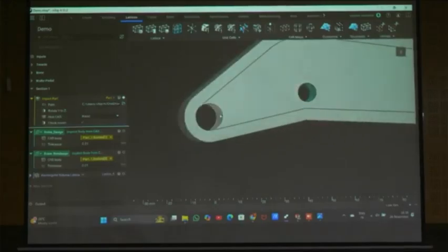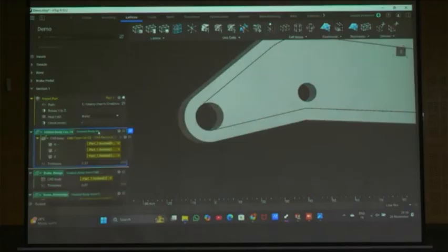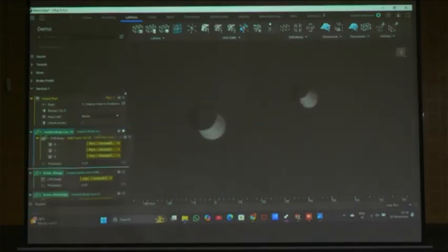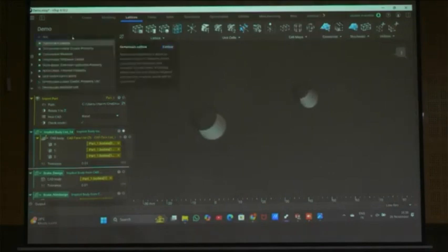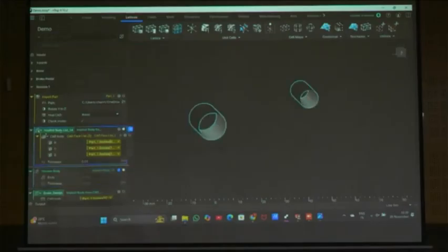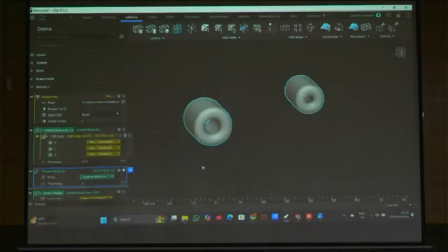Control, select the bodies. Convert CAD faces to implicit bodies. See, total 3 bodies are there. See these 3 bodies. So I can apply the thickness to the faces. This is the surface, right? So I will apply the thickness to the surface. Thicken body. So I will drag this. See, the symbol is same, right? I will drag this. I can apply the thickness 5 mm. This is okay.